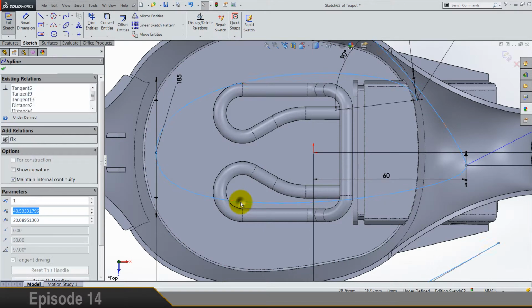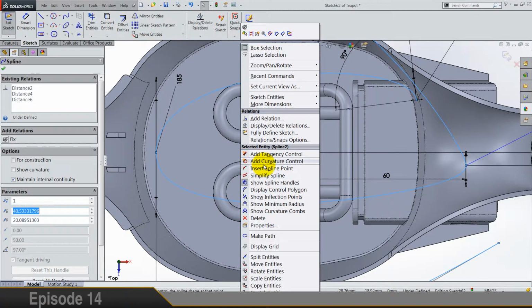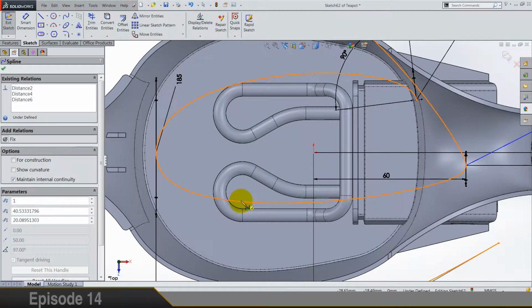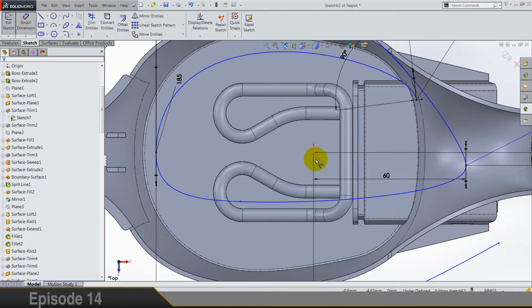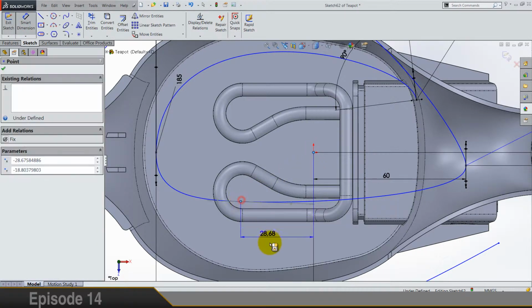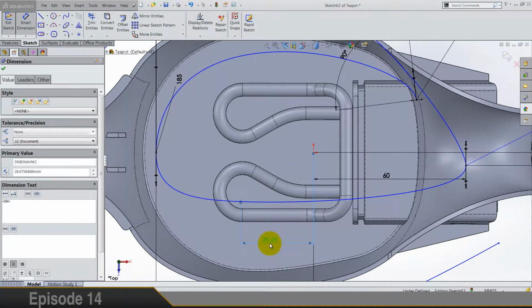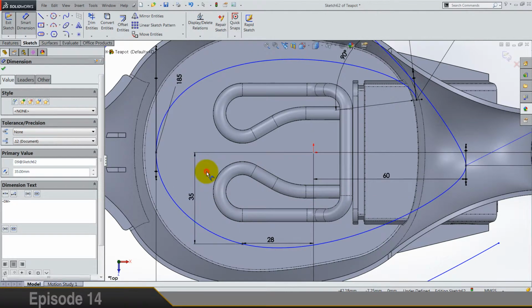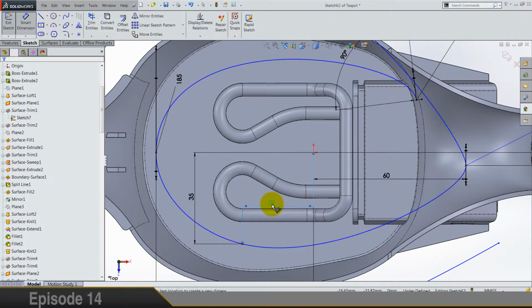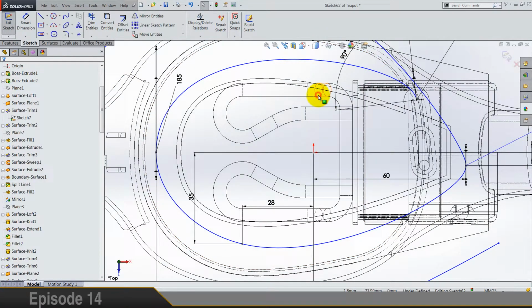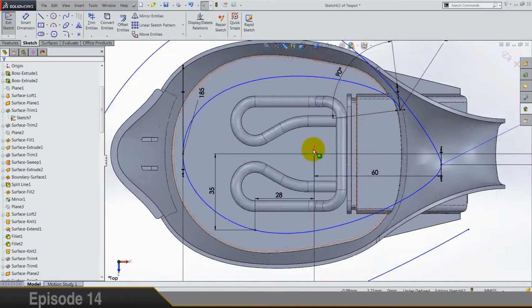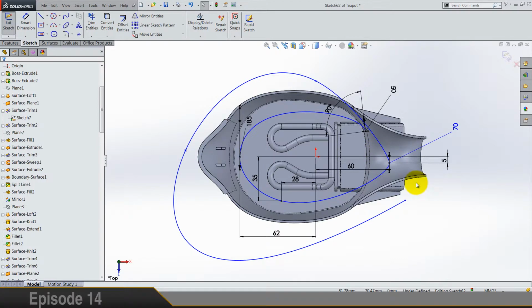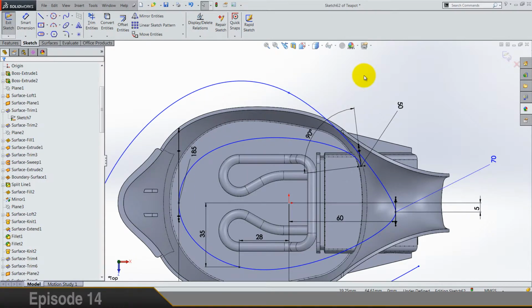Let's right click on the curve and insert a split spline point. So insert it somewhere around here. And let's put dimensions in, 28 and 35. So now it looks a lot better. Let's see like this. Yeah, now it's perfect. We are almost making it perfect.